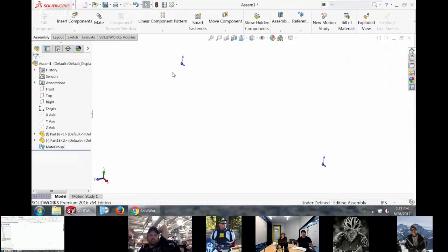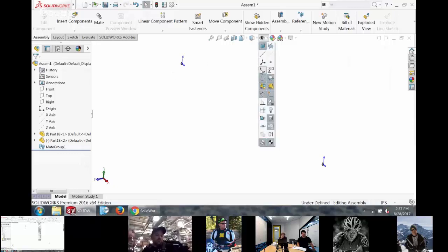So when I was in that sketch and I couldn't see my problem, I hit the fit screen and zoomed way out and I could see everything that was in the sketch. It's kind of the opposite thing going on here. You're in your assembly, you hit F, all of a sudden your assembly, you can't even see where it went. What happened is you got one part over here and then, 300 meters away, you have another part here. When you zoom out to see both of them, you can't actually visually see them. If I didn't have my origins turned on, I might not be able to locate those on the screen depending on how far they are apart from each other.